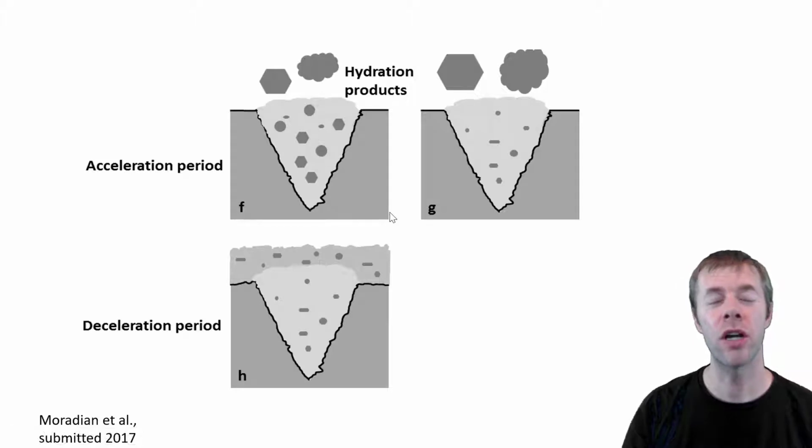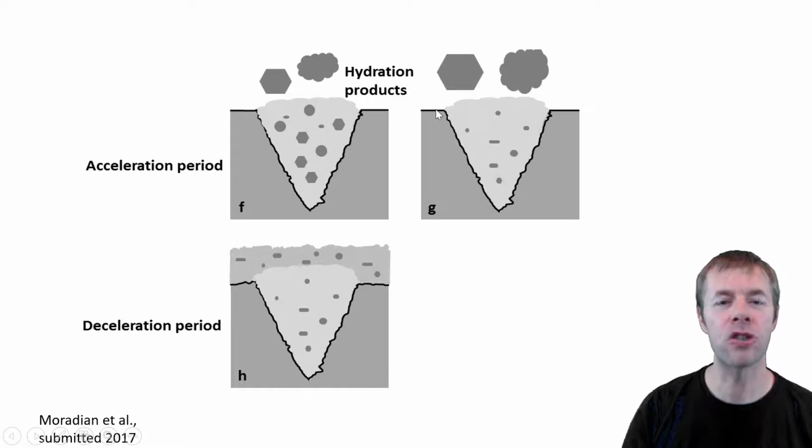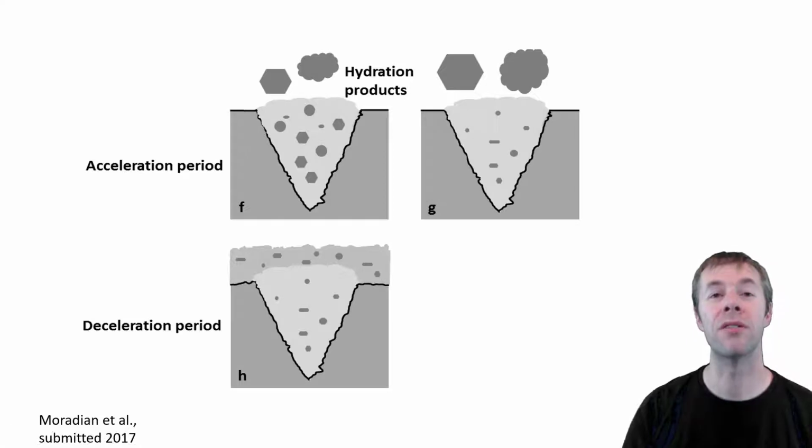And once they shrink and go away, reaction starts to happen again. The thing we don't understand yet, though, is reaction seems to happen in these pits, but it also starts to happen on these surfaces. These surfaces that didn't react before now for some reason become reactive, and we're not really sure why. And then hydration product starts to form everywhere.